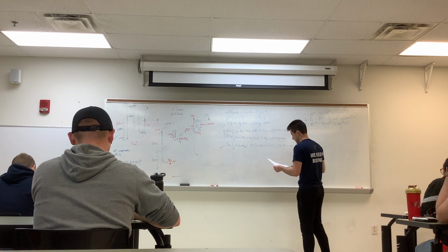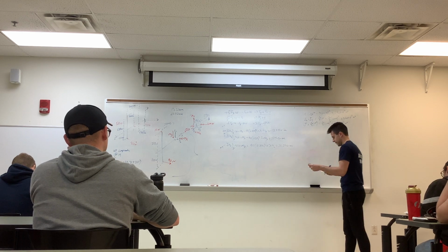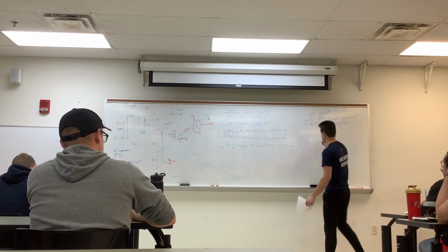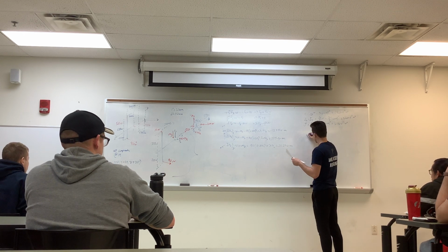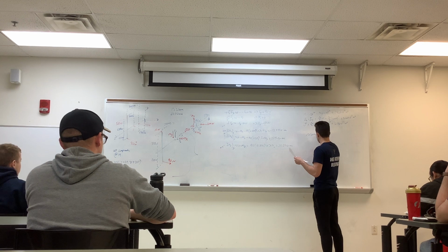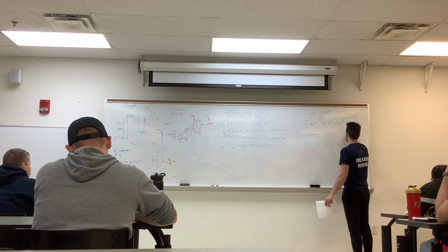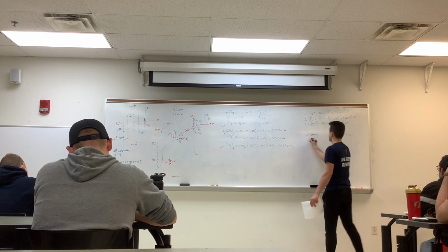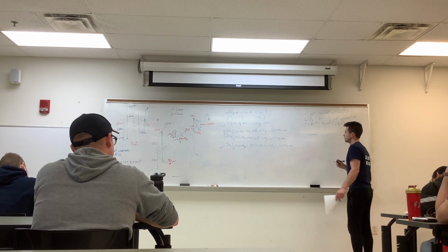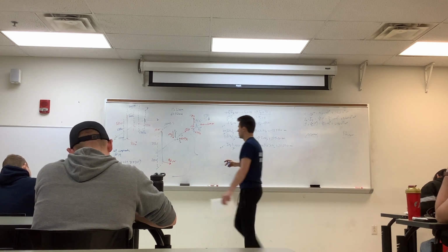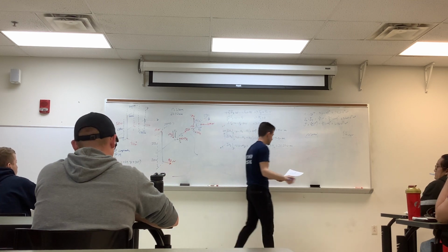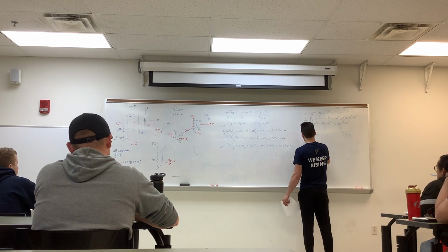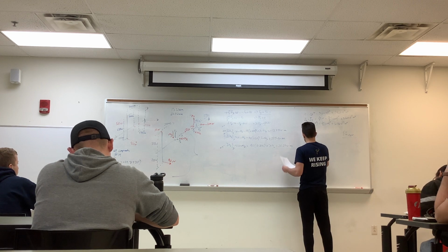Breaking down what causes our stress, what has been consistent throughout all of the problems: what causes normal stress, what causes shear. In the case of our problem, our force in the z direction is an axial force, so it will cause normal stress, so F of z.